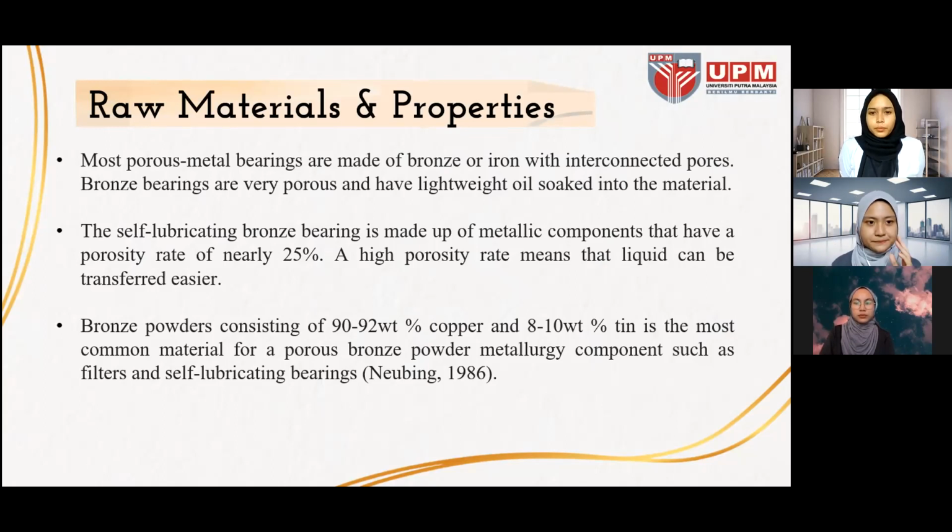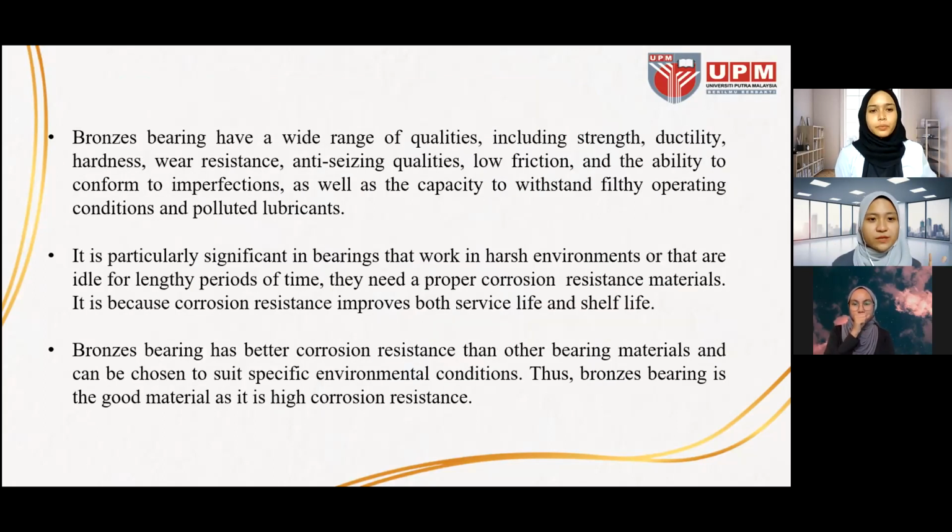So next. Bronze bearings have a wide range of qualities including strength, ductility, hardness, wear resistance, anti-seizing qualities, low friction, and the ability to conform to imperfection as well as the capacity to withstand filthy operating conditions and polluted lubricants. So the first property is corrosion resistance. It is particularly significant in bearings that work in harsh environments or that are idle for lengthy periods of time.